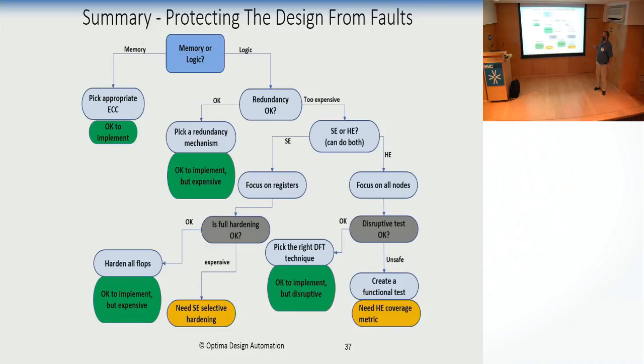Okay, if it's memory, just pick the right ECC and you're good to go. If it's logic, are you okay with redundancy? Are you sensitive to cost? If cost is not a factor, wonderful. Pick the right redundancy. It's okay to implement, but you said you don't care about cost. This is going to be expensive.